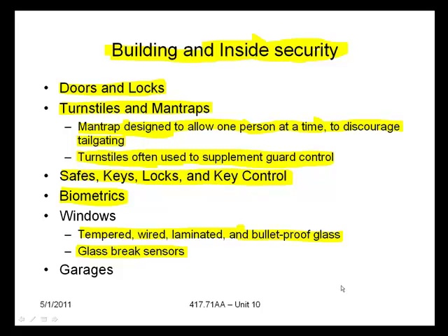Finally, attached underground garage and parking structures are something that need to be considered with interior building security. There are two primary threats there: crime and people getting run over by cars. Make sure that garages are properly designed for safety purposes in terms of directing people and segregating pedestrian and vehicle traffic. Use high lighting levels to illuminate the exterior of it and to illuminate areas with high pedestrian traffic, so cars are less likely to inadvertently hit pedestrians, and pedestrians may feel a lot safer.